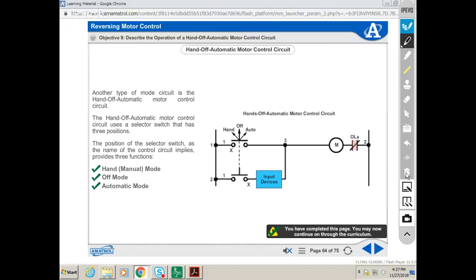What do I mean by a feedback device or control device? Well, let's back up. A feedback device typically tells me something happened, right? What is an auxiliary? Auxiliary latching contact. What type of device is that? Switch. It's a switch, but it's a feedback device that tells me that I pushed the contactor. It's only being used, and so it closes and it feeds back.